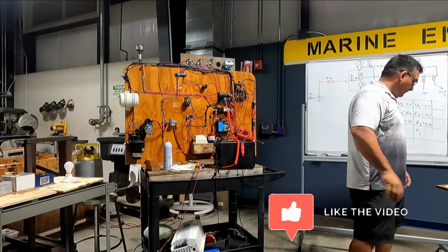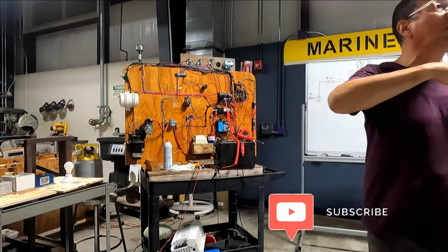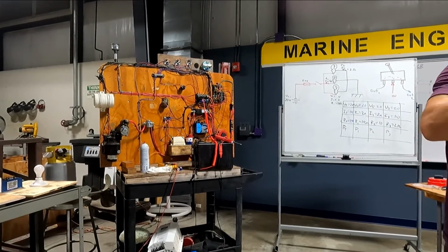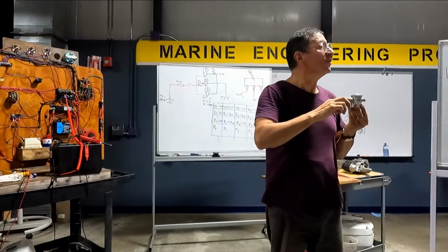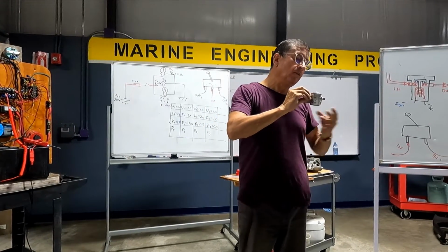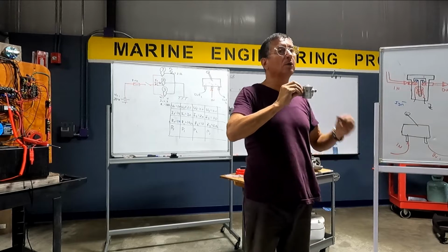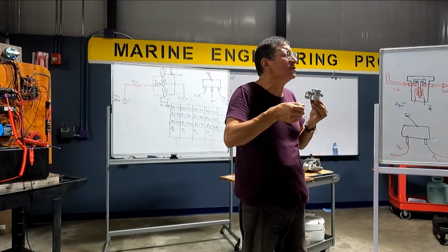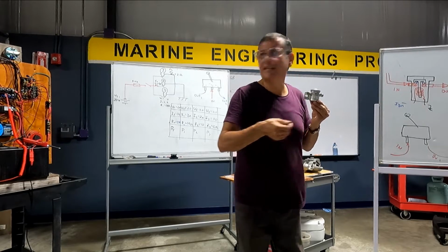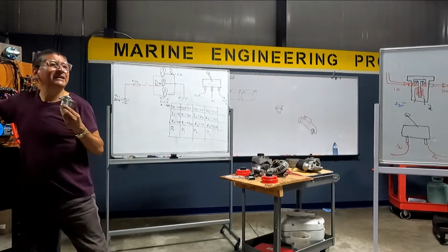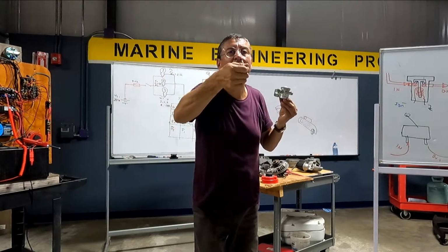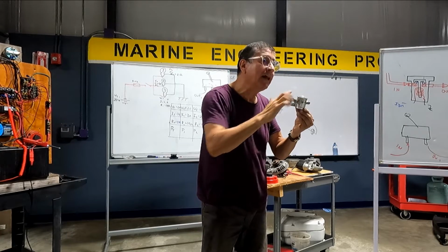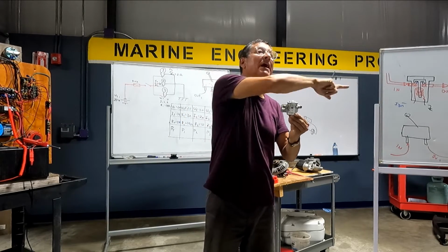Pay attention to this. I want to send a signal of 100 amps. 100 amps, how big is the cable? It's a big cable, no? I want to pass 100 amps through here to here. But I send a small signal. How much is the signal from the ignition switch? Is it 100 amps? No, it's 3 amps, 2 amps from the ignition switch. I send a small signal, close the gap, and the big current, 100 amps, passes through the other side.